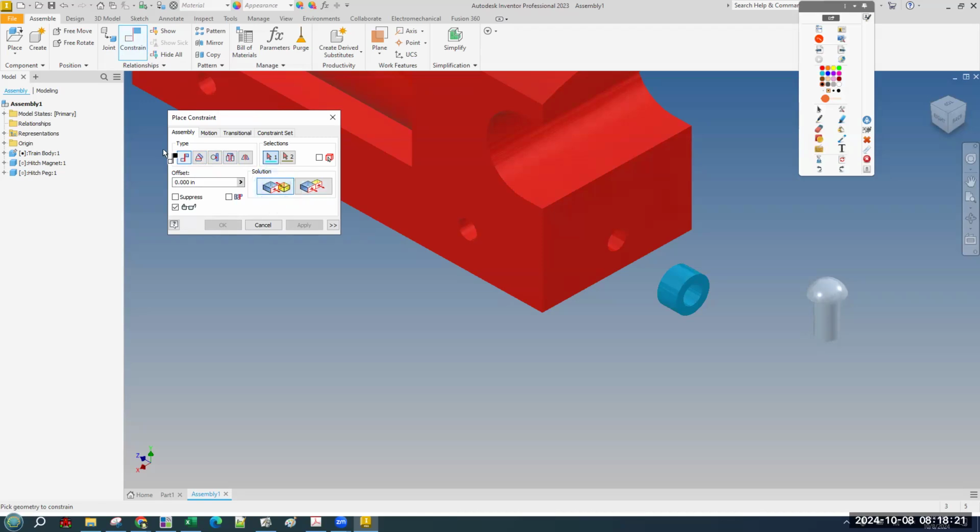It's sort of weird that mate is a type of mate, but we'll just have to go with it. It's sort of like this is a mate constraint unless you want them to flush. And you can see with this little pictograph, mate attaches things like you're gluing faces together, and flush lines them up so they're even facing the same direction.